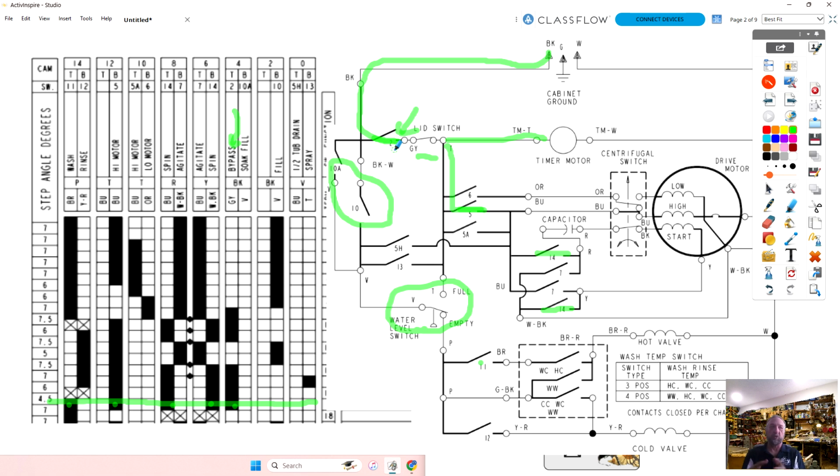Some manufacturers actually did it in the plastic mechanism. When the solenoid engages, it locks the door, but then when they want to unlock it, they pop the lock, unlock it, and move the lock lever again, which mechanically shifts it over. So not all lid locks are using a wax motor.